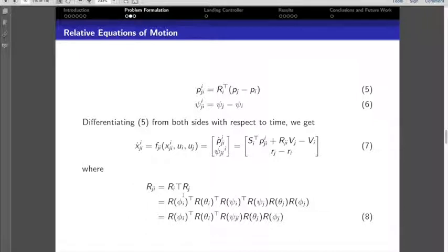It's simply you plug in the values of R_I and R_J, and then if you do the calculation, this part here becomes R psi JI, because we don't have individual psi I and psi J. We have individual phi and theta estimates, but we don't have individual psi I and psi J. So when you multiply this, you get a matrix called R psi JI, which only depends on the relative heading.